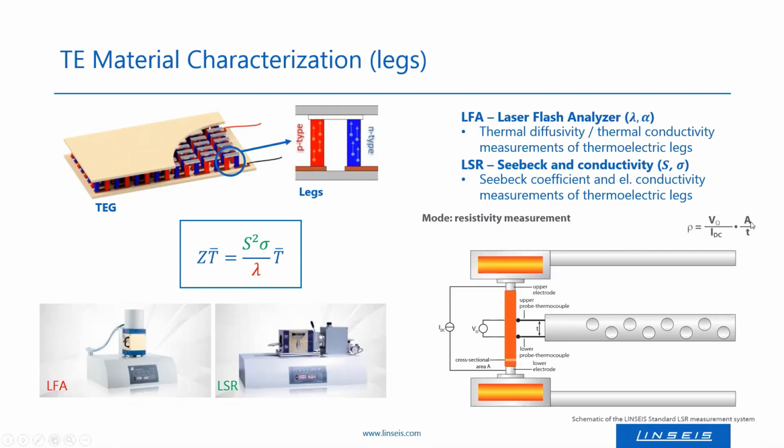For the calculation of the resistivity, one then uses this formula with all of the properties which I mentioned, and additionally one needs the cross-sectional area of the sample. So this measurement of the resistivity can then be used to calculate the electrical conductivity of the material. And a big advantage is that the Seebeck coefficient measurement and the resistivity measurement can both be determined in one run.